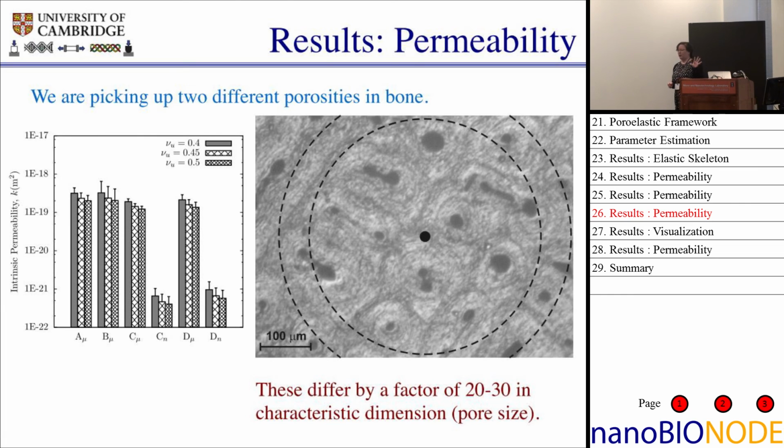So now our data make complete sense, because as we go to the very large contacts, we have lots of these macroscopic pores through which the fluid can flow, whereas when we go to our very small contacts and we're selecting where we're doing this so that we know we're not putting the indenter into one of these pores, then we get this much more difficult fluid flow. It's much more resistant because we're now not going through these big tunnels. We're going through the actual material itself. And the reason we don't see huge differences in the modulus between the two types of tests is, of course, because the total porosity is relatively small.